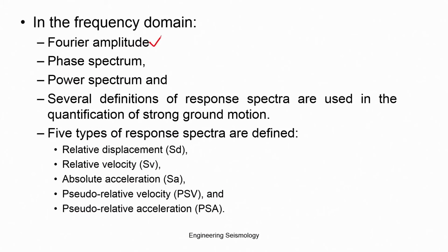The frequency domain parameters are the Fourier amplitude, phase spectrum and power spectrum. Several definitions of the response spectrum are used in the quantification of strong motion. The five types of response spectrum used are relative displacement, relative velocity, relative absolute acceleration, pseudo velocity and pseudo relative acceleration.